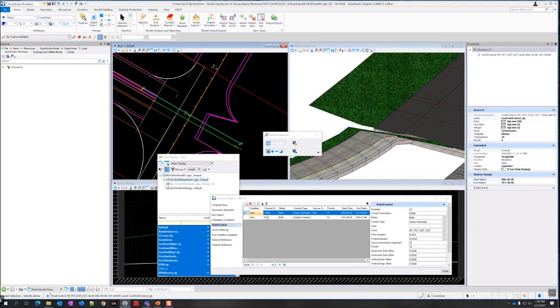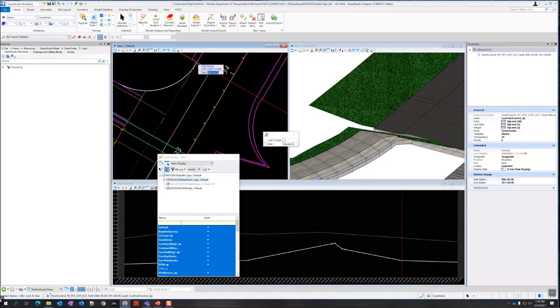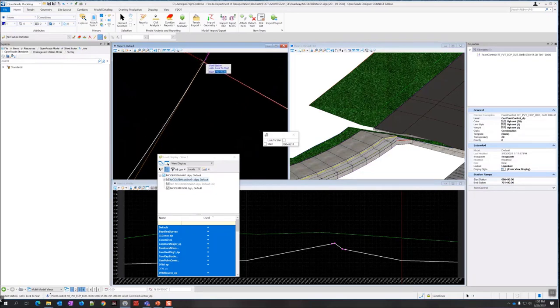And we're going to change this US 98 start station. I'm just going to select that. I'm going to do make graphical edit. So make sure you select it here so I can actually use the graphical edit. And instead of locking to start, first I'm going to just try snapping it to the end here.